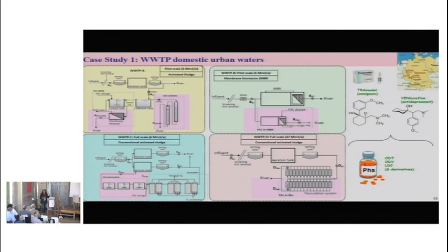The bacteria in these tanks are not able to degrade them, so in some cases the concentration doesn't even change. Here we have different configurations with granular activated carbon columns, also membrane filters, in this case with powder carbon in order to favor the filtration, and also some membrane reactors, where the carbon is in contact also with some bacteria.